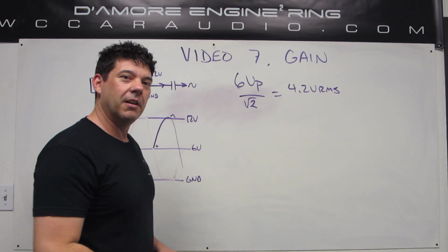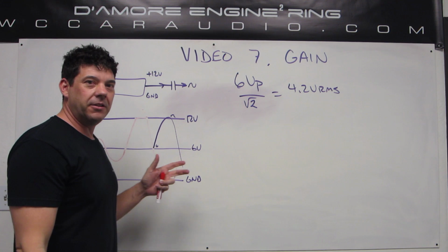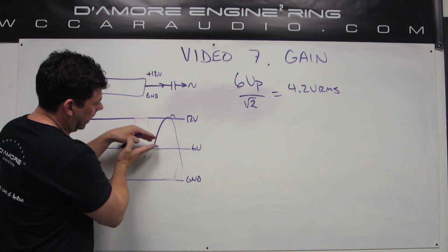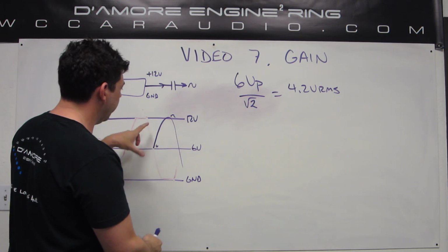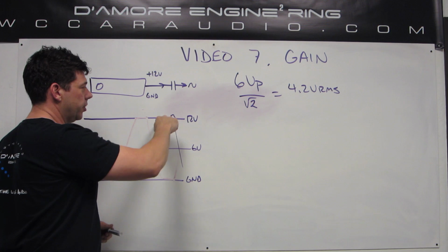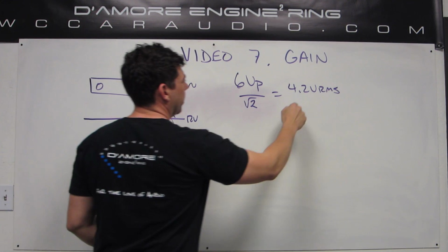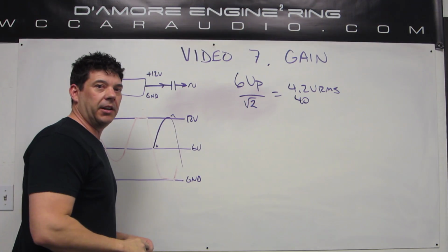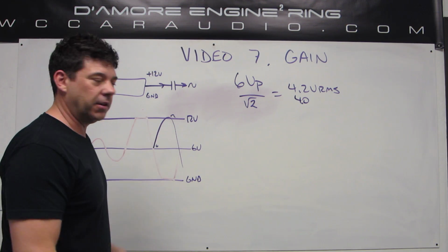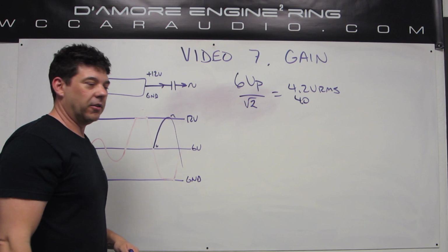And now you know why every head unit puts out 4 volts. There's nothing special. It's just how it happens because it's on a 12 volt car. There are some head units that only put out a volt or two because, I don't know why, they have some cheap parts inside that can't make it all the way to the rail, if you will. This would be called a rail to rail output, because the output device in here that drives the RCAs is good enough that it's able to push the signal all the way close to the rail and close to the rail. This is a best case scenario. You know, we're going to end up with about 4 because we're not going to get all the way to the rail. And like I said, some lesser head units will have some lower quality stuff in there, and they might only have 3 volts out or 2 volts out or something like that. But that's what's going on inside the head unit. That's why it puts out 4 volts.